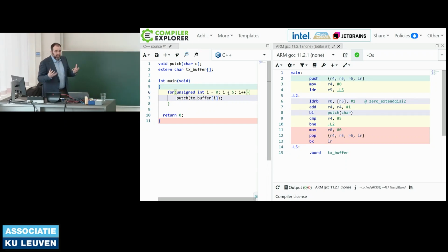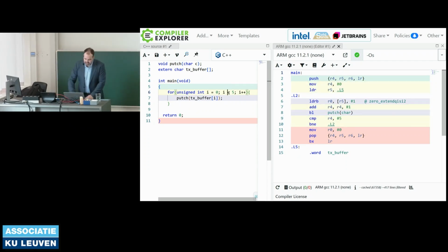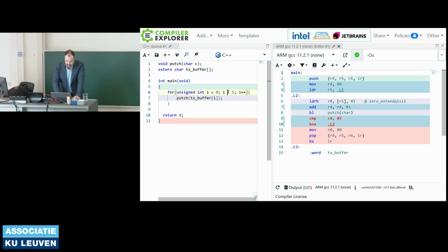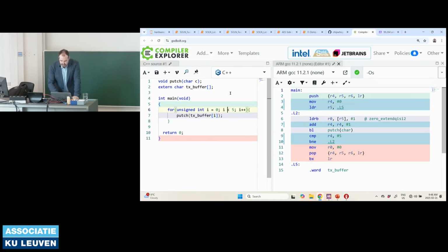But from a fault injection perspective, this isn't great, because if I can, for one loop, skip that instruction, so now I is equal to 6, it never saw 5, it's just going to keep looping through, right? So because of this tiny change, the compiler has actually made fault injection a lot easier for an attacker to do. That's one of the interesting things.